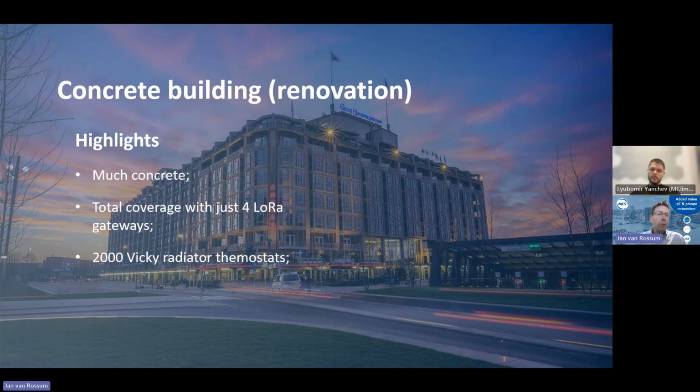So we need a few more gateways, probably around 10, but then still it's pretty cheap infrastructure to get this network running and monitor all the interesting energy and climate sensors. And indeed, in this specific example, we integrated the whole system into the local building management system. So the customer is able to directly control all his thermostats from all the information he gets from the whole system.